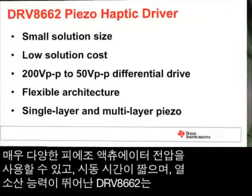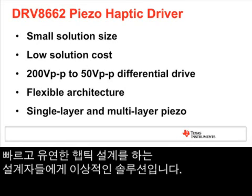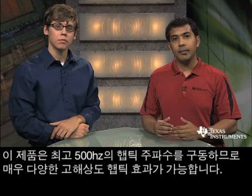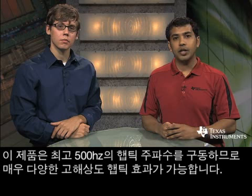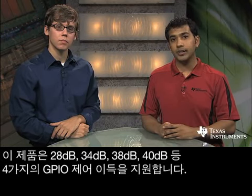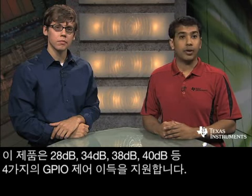The DRV8662 also costs 40% less than competing solutions thanks to a highly integrated design that eliminates the need for a transformer. With the capability to drive a wide range of piezo actuator voltages as well as fast startup time and excellent thermal dissipation, the DRV8662 is an ideal solution for designers creating fast, flexible haptics designs. It drives haptics frequencies up to 500 Hz, enabling a wide variety of high-resolution haptics effects. It supports 4 GPIO control gains: 28 dB, 34 dB, 38 dB, and 40 dB.